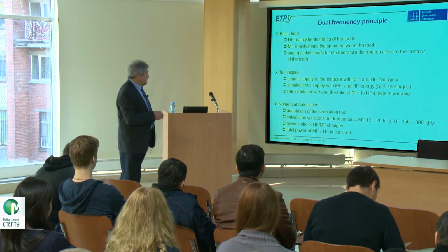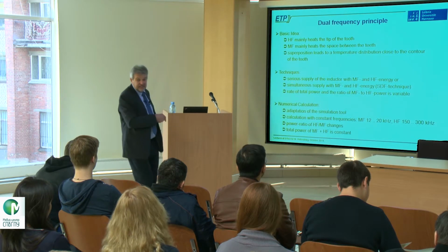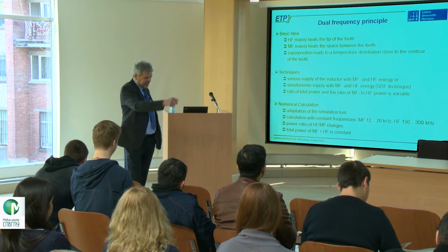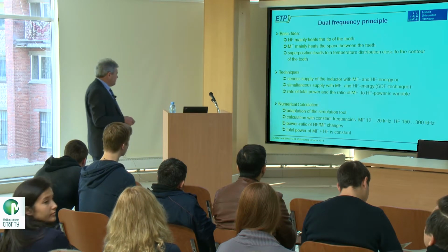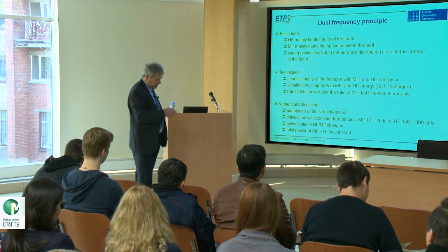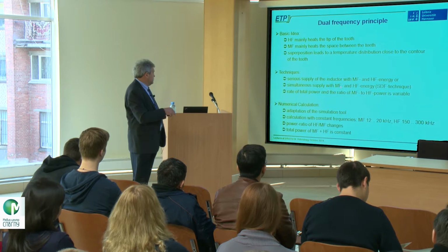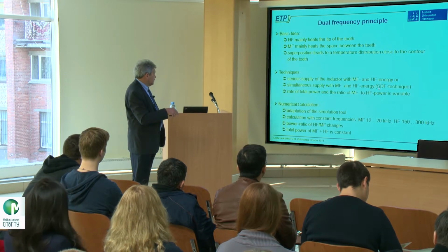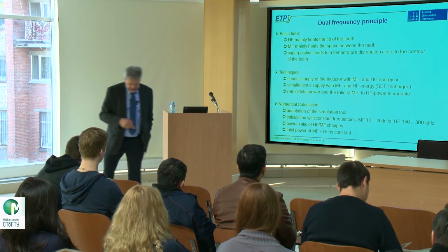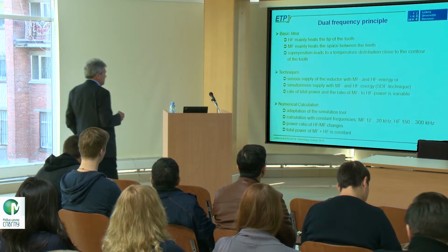There are some special techniques. You can use high and medium frequency serially. First medium frequency, and then high. But there are also some solutions, and also some patents, but they are finished now, to use it simultaneously. Simultaneously, of course, and this is the so-called SDF technique, simultaneous dual frequency technique. Of course, simultaneously is better.